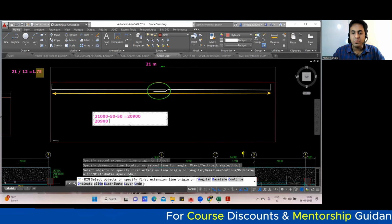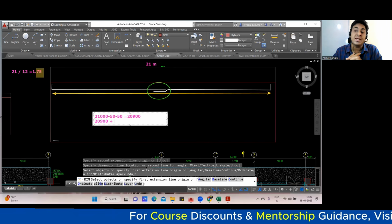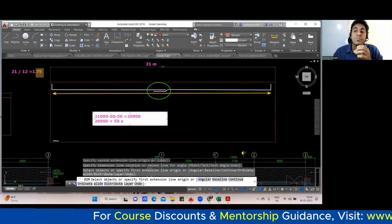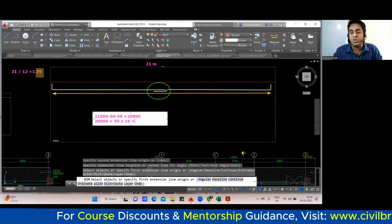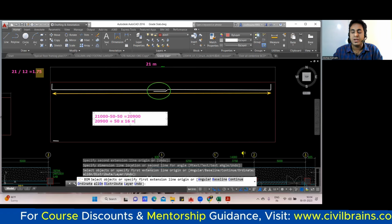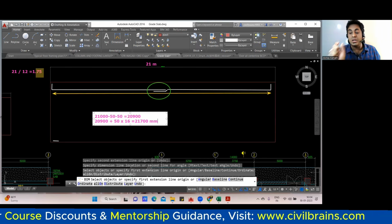20,900 plus lap length, how much you'll take? Let us say in the drawing it is mentioned 50 times the diameter of the bar. So I'll take 50, and let us consider I'm using a 16 diameter bar. So multiply this by 16. Tell me what is the answer you are going to get? Plus 50 into 16. Fine. So 21,700 mm. Fine. But this is only the straight portion.